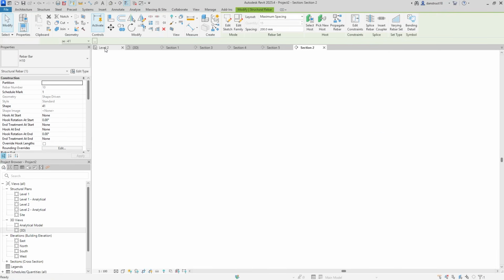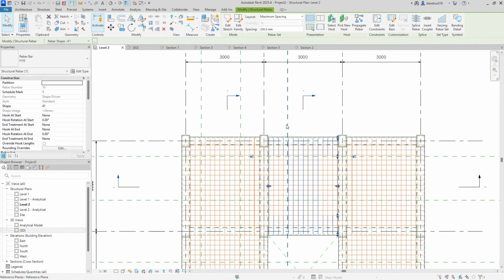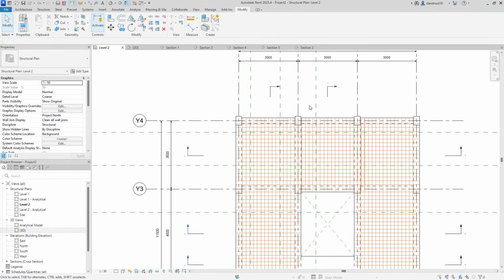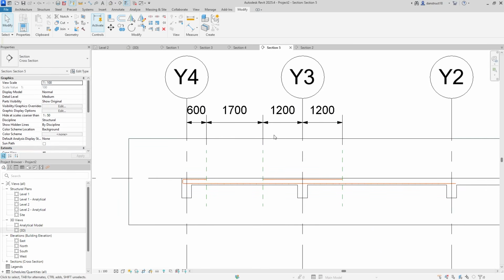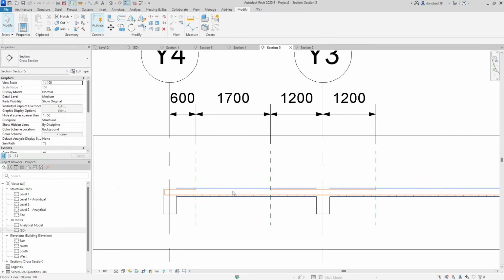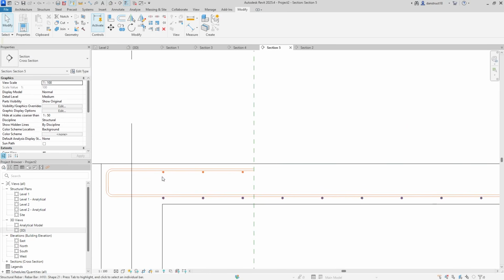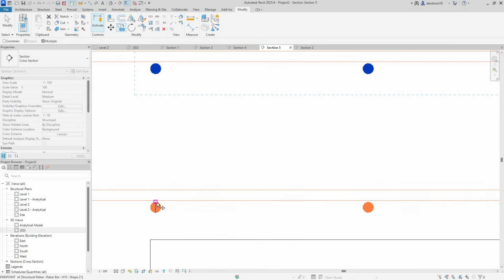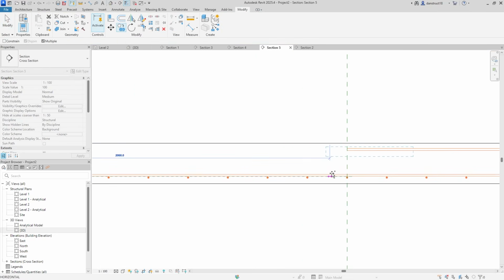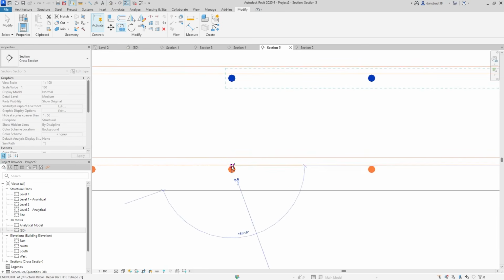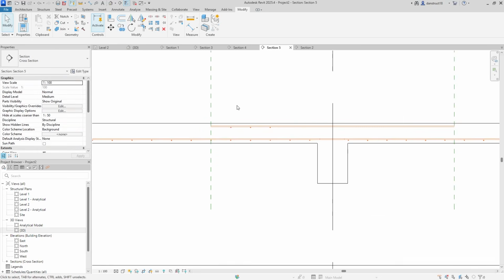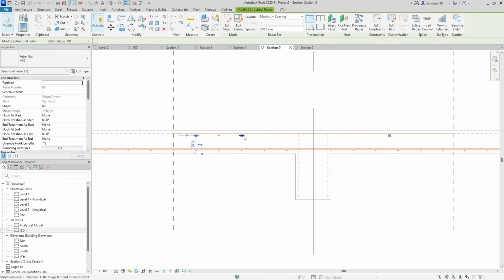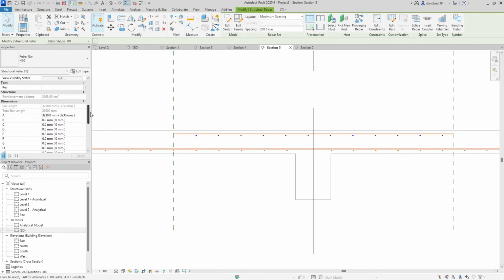All right. Good. Coming back here into the plan view, we also need to put the T2 reinforcements along that region. So I'm just going to go ahead and open up this section. All right, great. And we can see we don't have T2 reinforcement here. So I'll just go ahead and select this one here. I'll go to copy, and then I'll copy from this reference point, and I'll come all the way here and paste it. Great, good. Click on modify, and I'll just go ahead and select the reinforcement, and I'll drag it out all the way to the other point. There we go. Right, good.